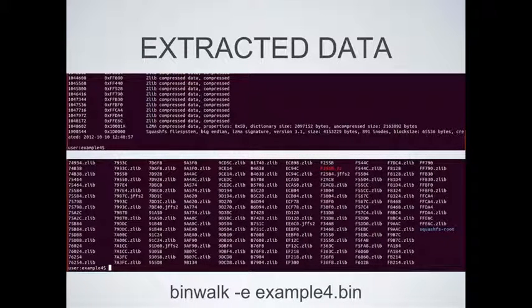And what you do after you get the data out of SPI Flash, it dumps it to a binary file. Then you can feed that binary file into BinWalk and have it extract. If you use the -E option, it'll extract what it can, and it can parse the firmware headers, and it can identify sections that are possibly compressed and decompress them for you. And underneath, it's actually calling Sasquatch. Sasquatch is calling unsquashfs underneath, and then you get this nice output.